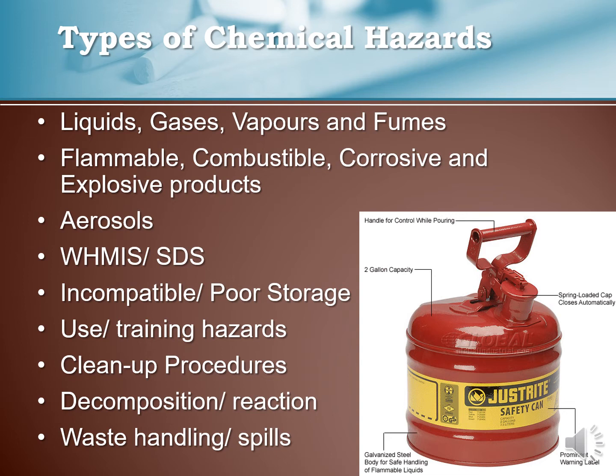There may be a hazard with gasoline or diesel stored in an improper jerry can instead of the safety can as pictured. These cans are required when gas is stored inside our facility outside of a flammable storage cabinet, or when gas is dispensed indoors. It may apply in custodial, transportation, manufacturing, or construction areas.